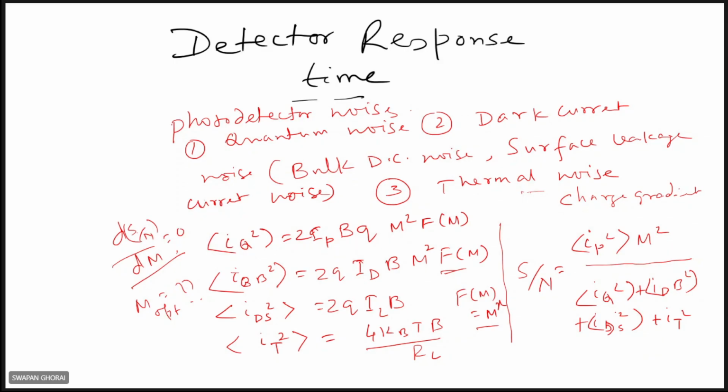But when the signal is very weak, say for single mode fiber, you have to use the avalanche photodiode, where the avalanche effect gives carrier multiplication and internal gain. We also saw important parameters of PIN and APD photodetectors: responsivity, quantum efficiency, and response speed.